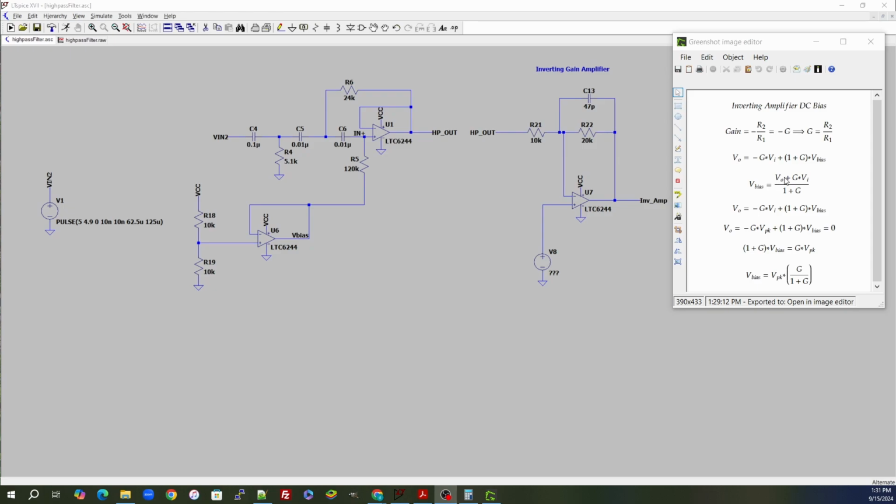And when we start looking at the formulas, which you can see right here, our bias voltage, because what we want to do is on the output voltage here, in this formula right here, right? Since it's an inverting amplifier, whenever we reach our peak voltage of the output of this high pass filter, that's when we want to register a 0 on the output of the amplifier, right? Because then it'll be sufficiently biased so that we're getting the whole signal going through this inverting amplifier.